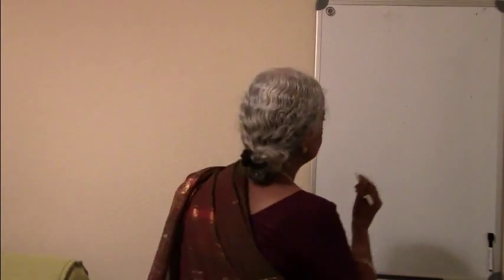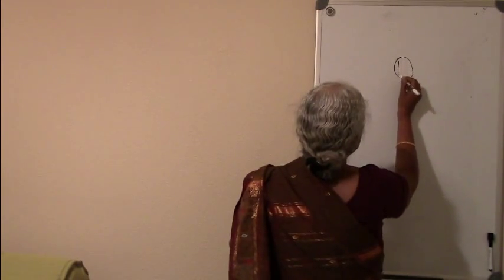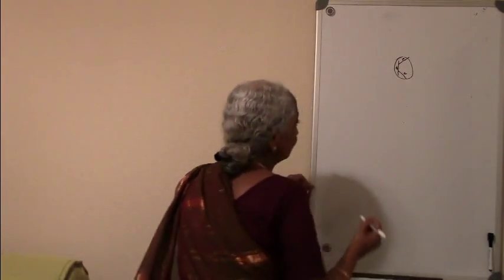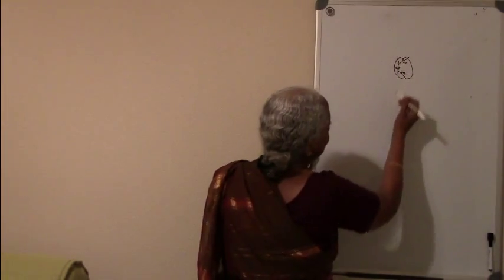Therefore, I will just give you the circuit. But even while drawing the circuit, remember that the emitter should be forward biased and the common terminal of the collector should be grounded, and the emitter should be forward biased, and the collector should be reverse biased. Yes, so the circuit will go like this, because the collector has to be the common terminal. You draw like this, the collector is here, the emitter is here and the base is here, and it is an NPN transistor: N for emitter, P for base and N for collector.